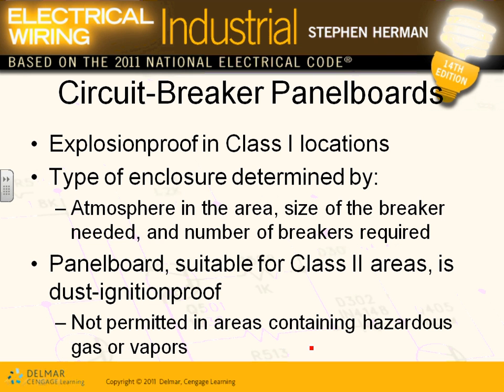Explosion-proof equipment. So circuit breakers and panels. If you put your circuit breakers on a panel and any equipment, what do you guys think the circuit breaker has to be rated for? Explosion-proof Class 1 Div 1 in a Class 1 location. The enclosure is the area size, breaker, and number of circuits. So all these you have to take into consideration. I'll show you a couple of panels that you can go buy right now if you want to, explosion-proof.